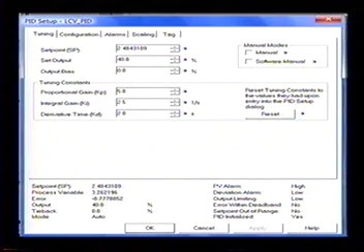And the way you would tune this, the easiest way to do this is once you've manually made sure everything flows properly, right? You know that you've got enough water coming into the tank, and you know that given the valve position at 75% open and the tank run and the pump running, that everything's kind of stable. It's neither increasing real fast or decreasing real fast. It's kind of stable. So now you know you can actually control it.